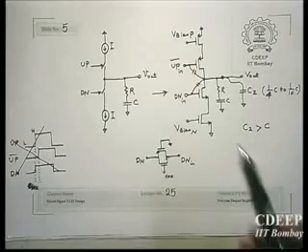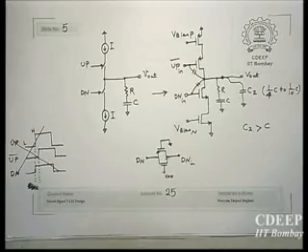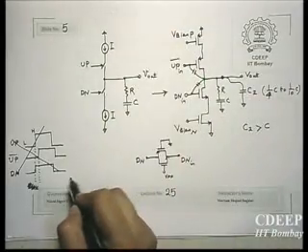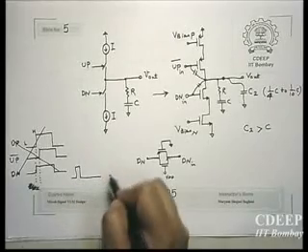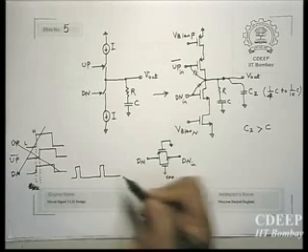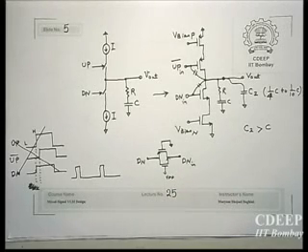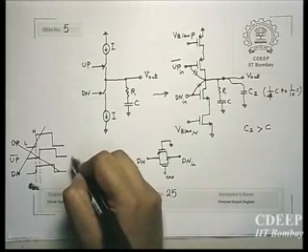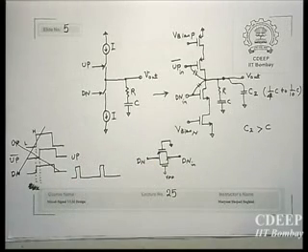For example, we had this case when you have a phase difference less than pi. You will get some kind of waveform for up, and then down will be almost 0. Now when up is 0 and down is also 0, of course both of them are off. Then when up is 1, you will receive some current.